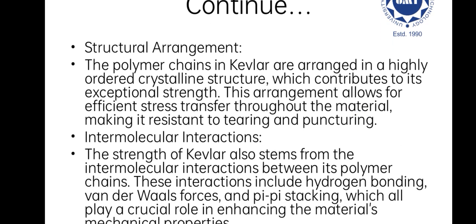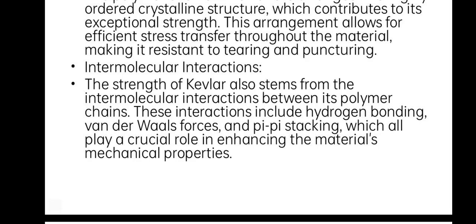Now let's talk about intermolecular interactions. The strength of Kevlar also stems from the intermolecular interactions between its polymer chains. These interactions include hydrogen bonding, van der Waals forces, and pi-pi stacking, which all play a crucial role in enhancing the material's mechanical properties.